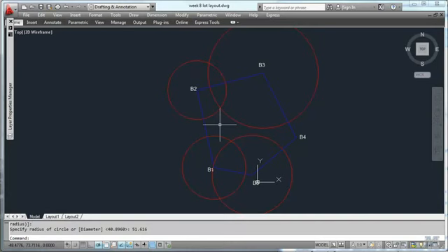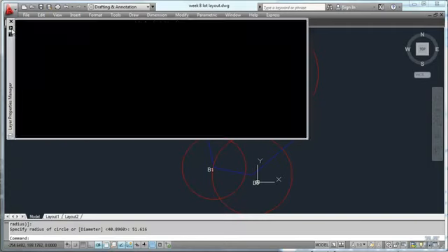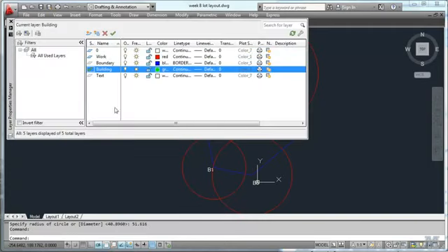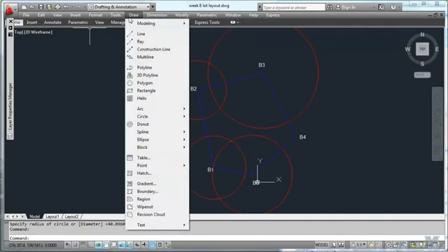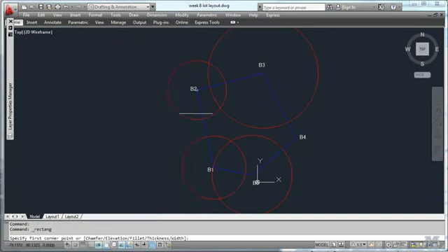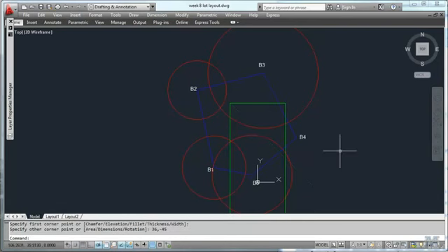Let's then put the building in here, and I'm going to switch layers again. Make that my active layer and building, and draw in a rectangle. And that's going to be, I'm just going to throw it in here and then adjust it. So let's go, it is what, 45 feet, 36 feet, so let's do 36 comma minus 45, kind of put it in the right orientation. I think I messed up because that is not using absolute coordinates.